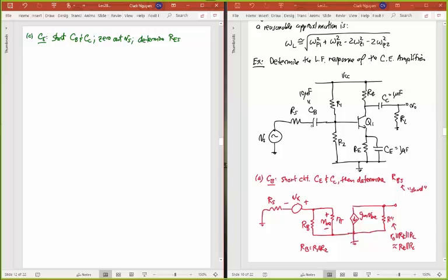And so in this circuit, C sub B is going to be shorted, so I'm going to see RB going down here and RS going there, and I'm going to short out my VS. I just shorted it out. So I have RS here. I have RB there. I have my R pi, and my VBE across that R pi.